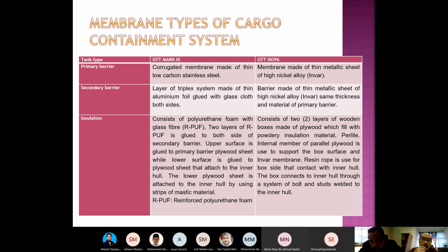Normally this tank is a very big tank for an LNG carrier. Just now I mentioned, how do you address the effect of free surface? I think you mentioned it, but it was not very clear. The filling, as you mentioned, is about 80% maximum, of course to allow the expansion of the gas.